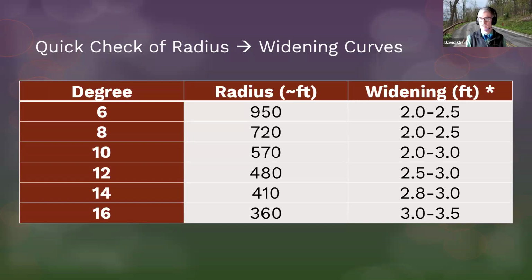In fact, on campus, the speeds are low enough, it wouldn't kick in. It wouldn't kick in to widen it, make it worth it, because it's not worth it if it's pretty narrow, until you get to, I think it's 40 or 45 miles an hour. Now, if you had a pretty flat, pretty sharp curve, you didn't even need it on a low volume road, like a 16-degree curve. You might want to think about that. So in your urban areas, that's part of the reason we have to cut the corner. We have to think about how trucks and vehicles actually travel.